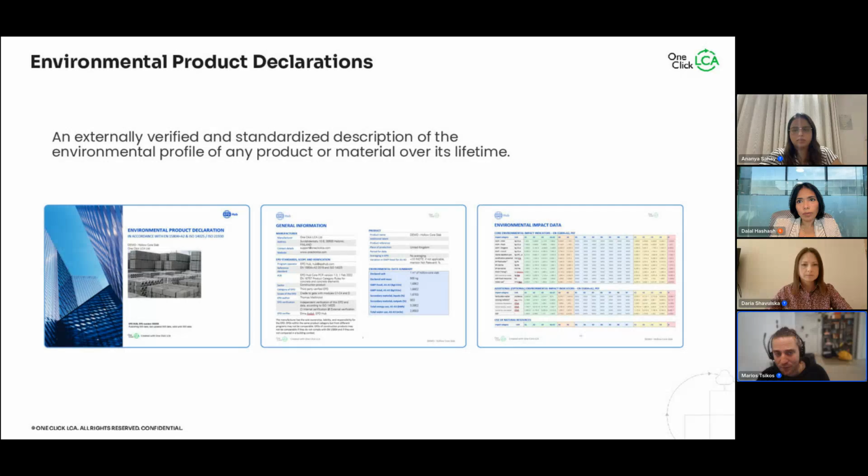I mentioned environmental product declarations already. This is a product LCA. It is an LCA that the manufacturer will do for their products. So we then, as sustainability consultants, architects, structural engineers, can use and do these calculations. The calculation concept is extremely simple. It's basically our material quantity times a carbon factor or other impact factor. It's a simple multiplication. Well, it's a very simplified way to put it, but it is something like that. It's always some kind of multiplication.